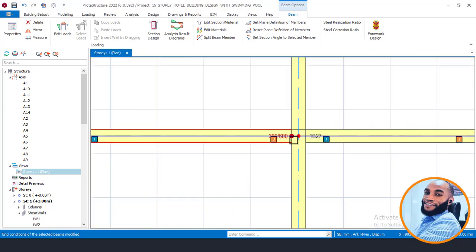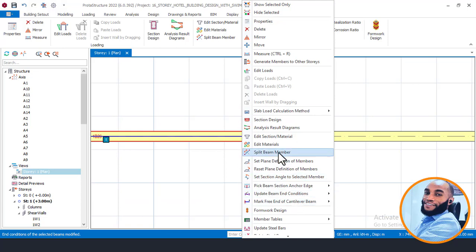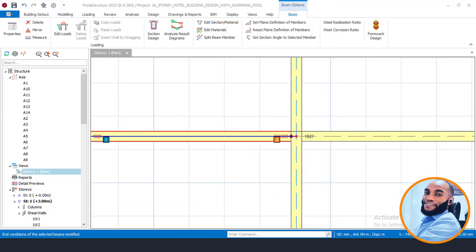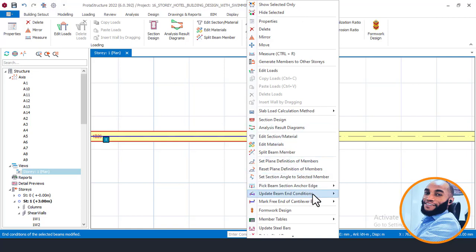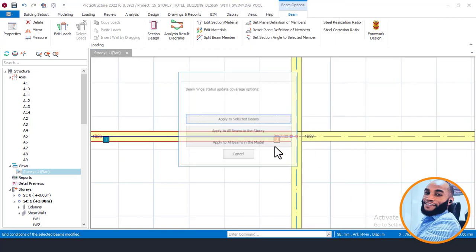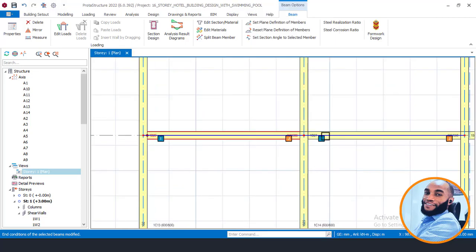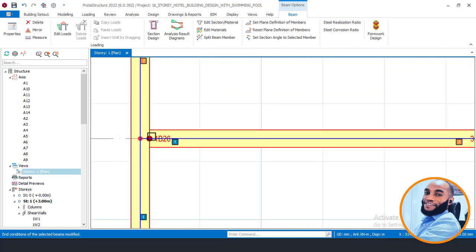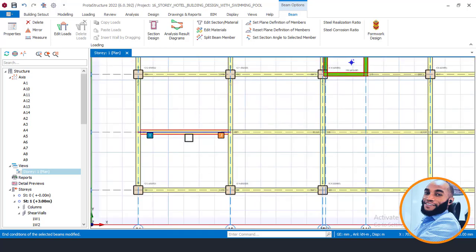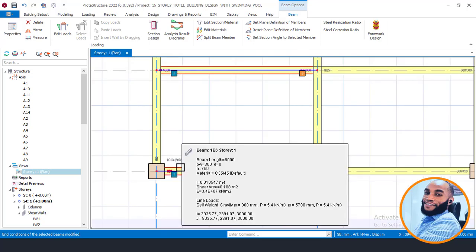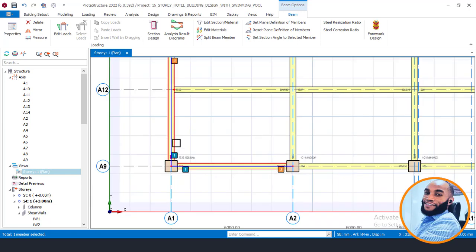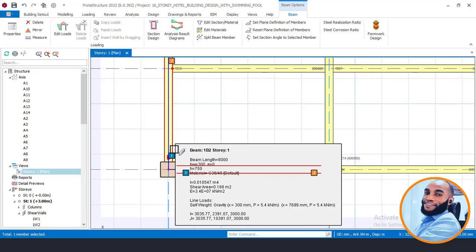Okay, no, not this end. Basically the I end. So I'll come here, click here, right click here and then say apply to I end, and then say apply. It will now show a dot here. This dot here simply means hinge. So I'm trying to release the moment from this place, because basically from the theory of your design and analysis, every beam end is meant to be released, and that place should carry zero moment. Okay, so right now I will hinge every beam end.